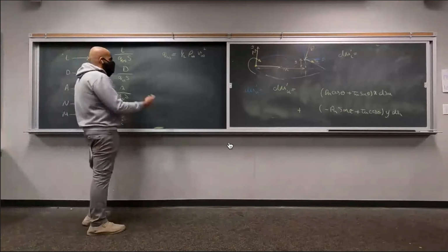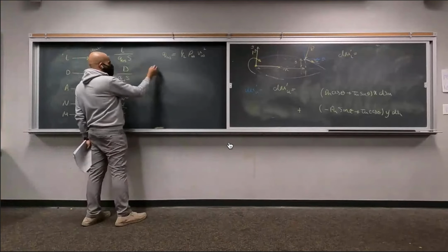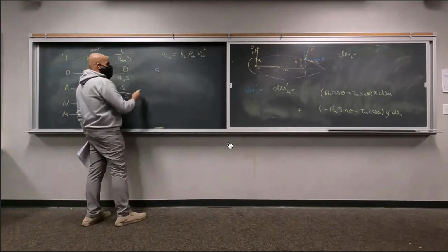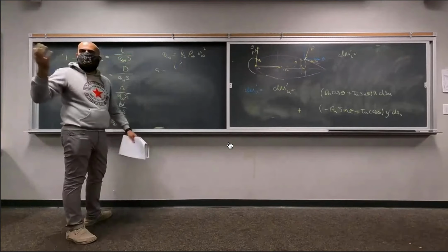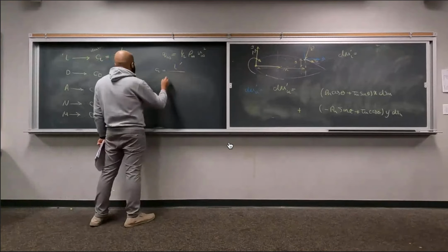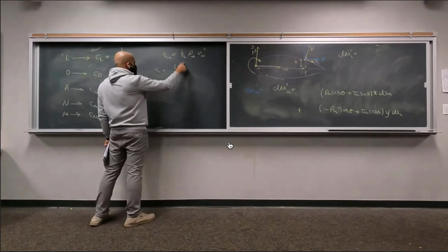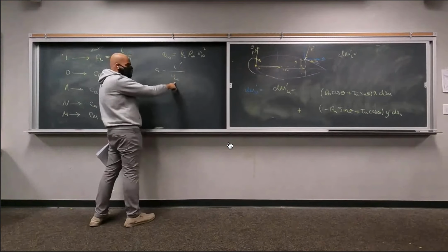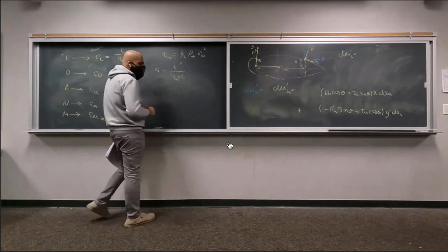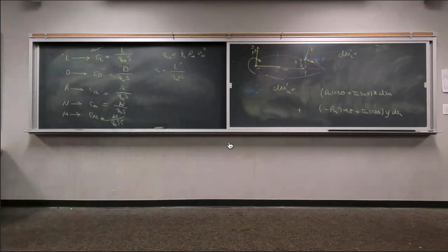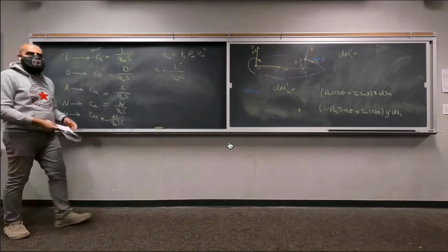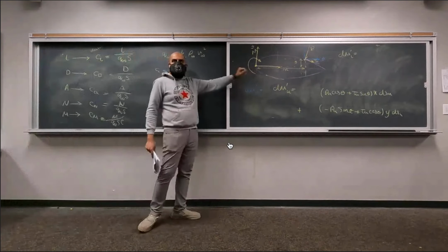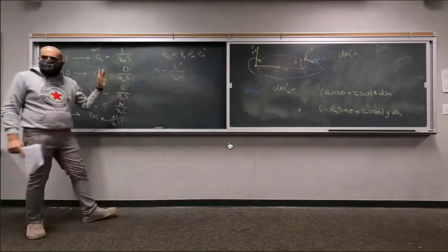So if you are dealing with a two-dimensional case, we are going to use a small c instead of a capital C, and then your per unit span force that you have calculated, divided by Q infinity, is newtons per meter over newtons per meter squared. So we are just going to multiply this by the chord length, or the average chord length if it's a wing. But it's a two-dimensional case, so we are only going to deal with the section of the wing or an airfoil. Does this make sense?